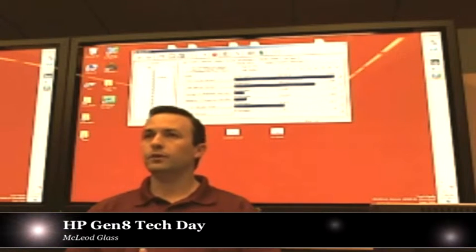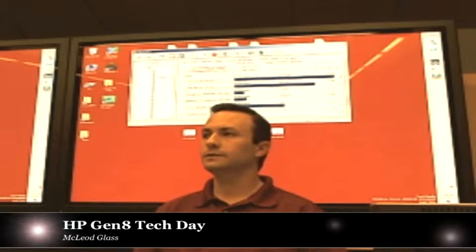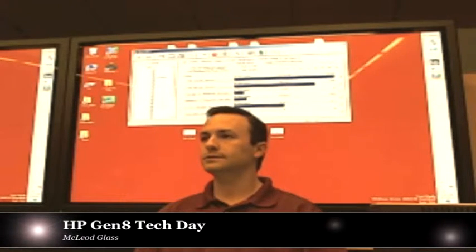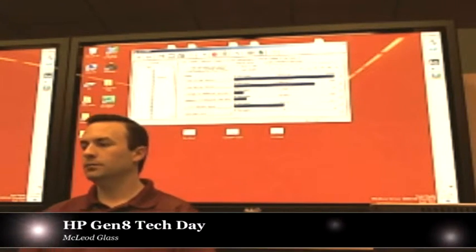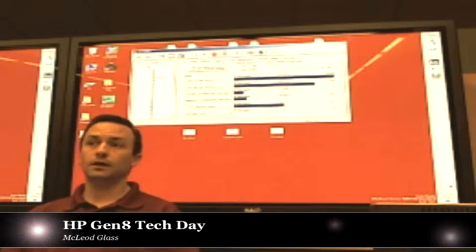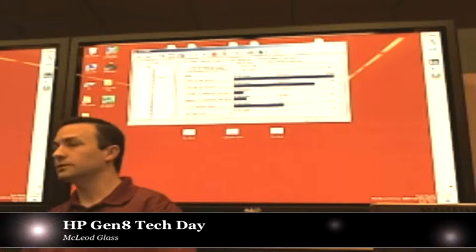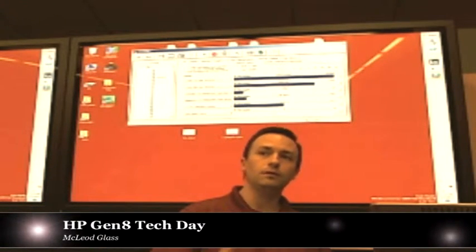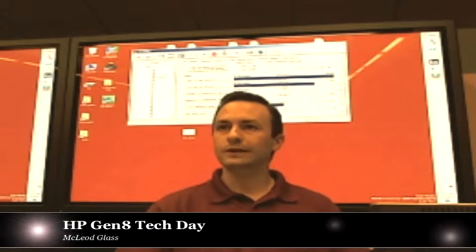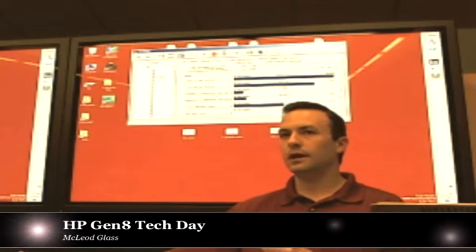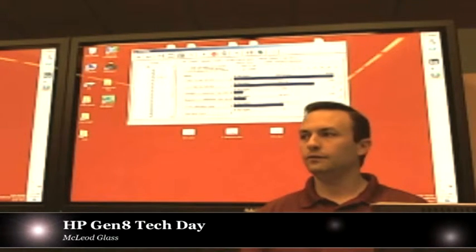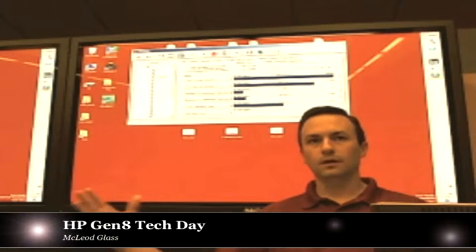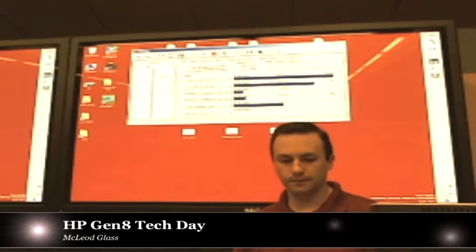Particularly with our P42X generation of controllers, we have increased our RAID 5 and RAID 6 write performance by about 2x. If you look at the previous generation, the P410, we were pushing about 1 gigabyte per second, give or take a few. And with this generation of controllers, we're pushing over 2 gigabytes per second. So we've doubled that bandwidth. And so increasing our IOPS by 4x, by doubling our DRAM bandwidth, that's how we've optimized for the explosive performance that is available with solid state drives.